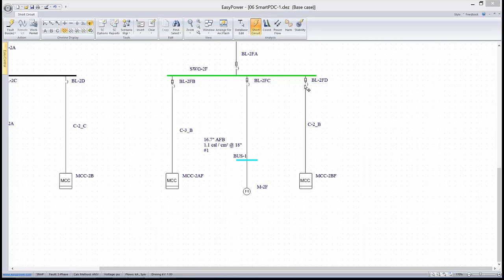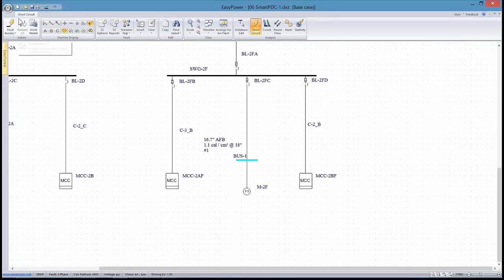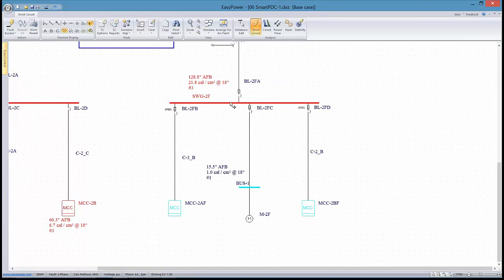in that the energy on this particular bus actually could be decreased as we remove loads from the bus, and that would be a procedural call, if you will. You can see that the arc flash boundary is decreasing. It might be a procedural call that if we had to work on this bus while it was still electrified, reducing the loads on it might bring the PPE down, or the incident energy down low enough that we could work on it with less danger to personnel.